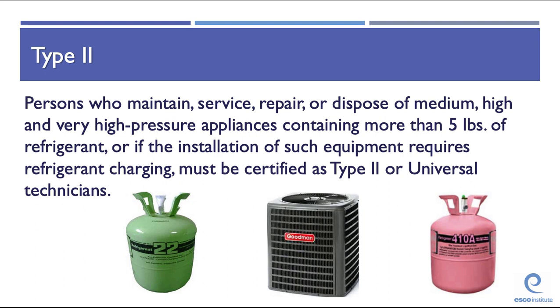Type 2 certification: persons who maintain, service, or repair or dispose of medium, high, and very high pressure appliances containing more than 5 pounds of refrigerant, or the installation of such equipment requires refrigerant charging, must be certified as Type 2 technicians. It's important to understand the refrigeration pressure of each certification category. Type 2 certification includes medium pressure, high pressure, and very high pressure appliances. If a system requires refrigerant line connections or charging in the field, even if it is less than 5 pounds, the technician must be certified as Type 2.